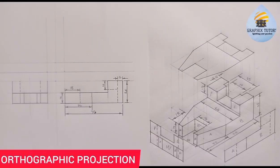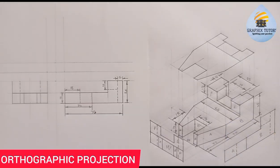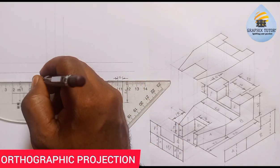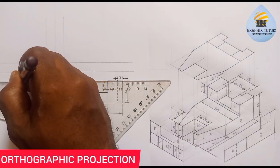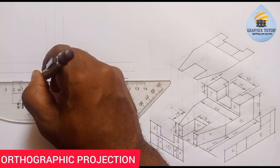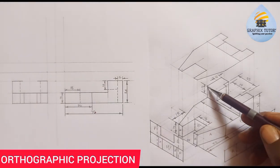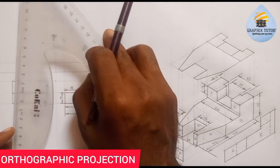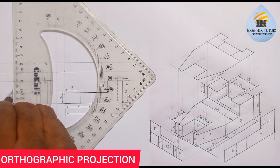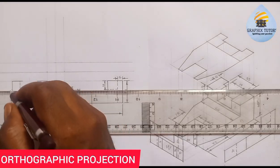So aside from that, the next one is 19 to get to the next point. So you're going to measure 9.5 on both sides. From 0, this is 9.5 here, and this is another 9.5 here. So you just join it to this point. You come again, you join it to this point. Can you see that? Now the next one is you measure 10 downward. So from 0, you measure your 10. This is a 10 here, right? And use your instrument. Just draw a faint line this way.